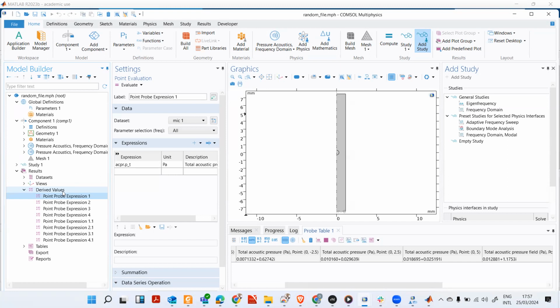Yes, exactly. And COMSOL, you can just treat as a normal MATLAB function you want to create, and then you can call it multiple times without opening up this console. Actually, it runs faster than directly running inside the console, because it doesn't have to open this graphic interface for you.